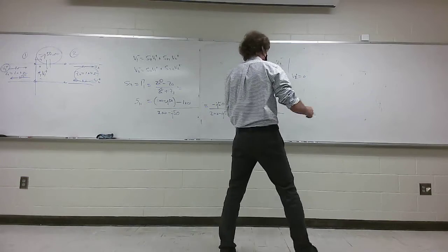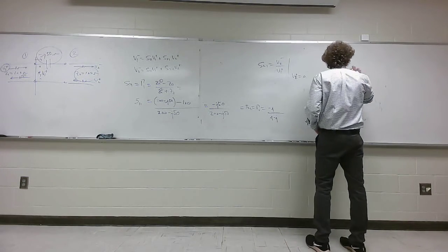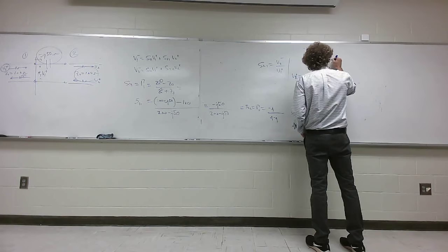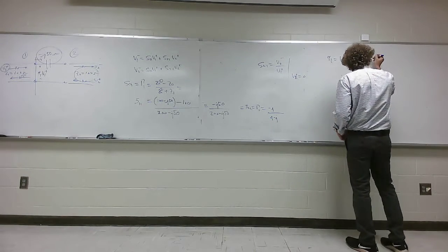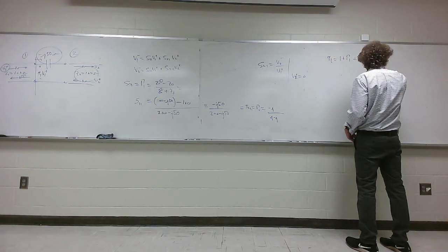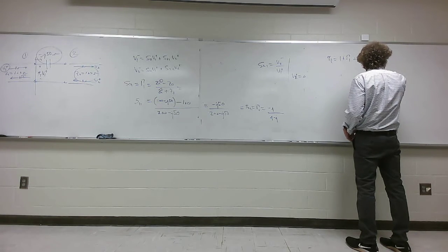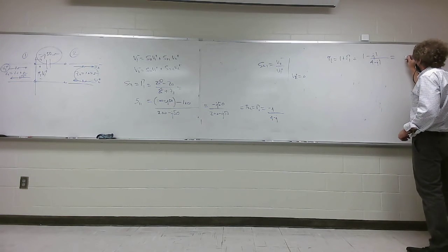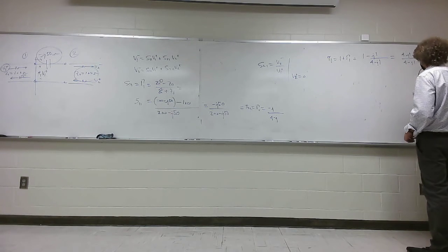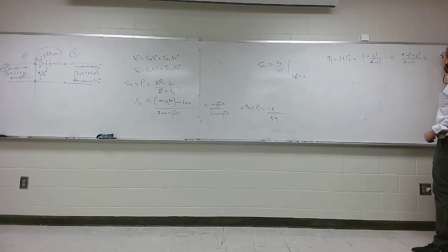Now I'd say, and this is the last point I'm doing that, the transmission coefficient of port 1 would be 1 plus the reflection coefficient of port 1, or it's 1 minus j1 over 4 minus j1. You could say this is really 4 minus j1 minus j1 over 4 minus j1 if you wanted to, and you would have simply 4 minus j2 over 4 minus j1.